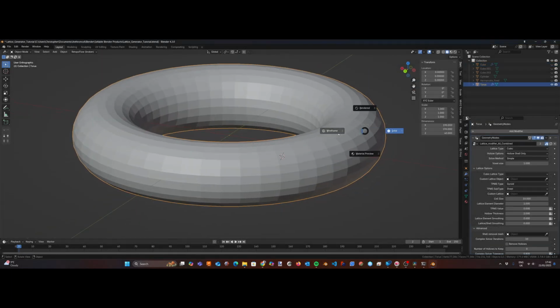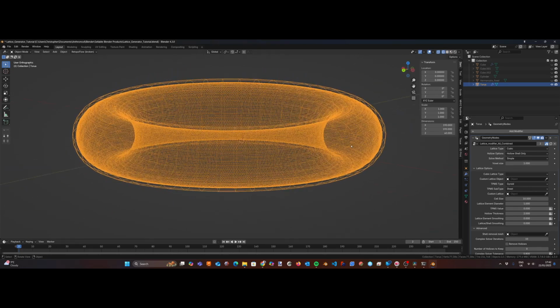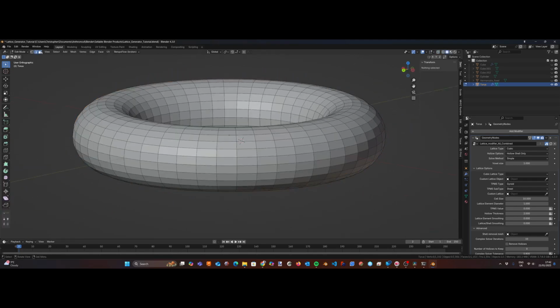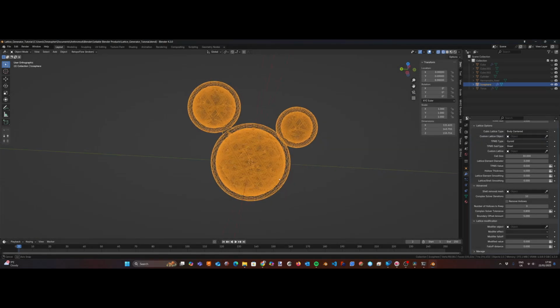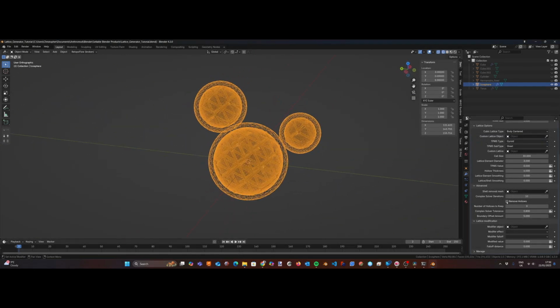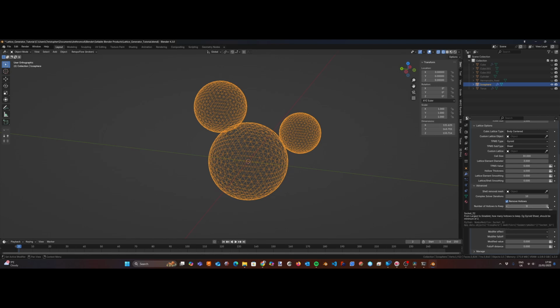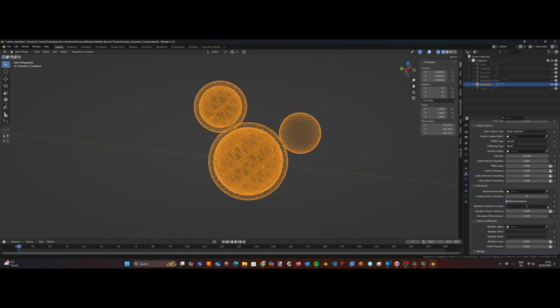Here there are options for how the hollowing operation works. I developed a simple and a complex solver. The complex solver allows non-ideal objects to be hollowed, for example objects with small holes in them. Here is an option to remove small hollows, which means it can remove small hollow regions in the part. It's useful for preventing issues like resin getting trapped within voids of resin parts.